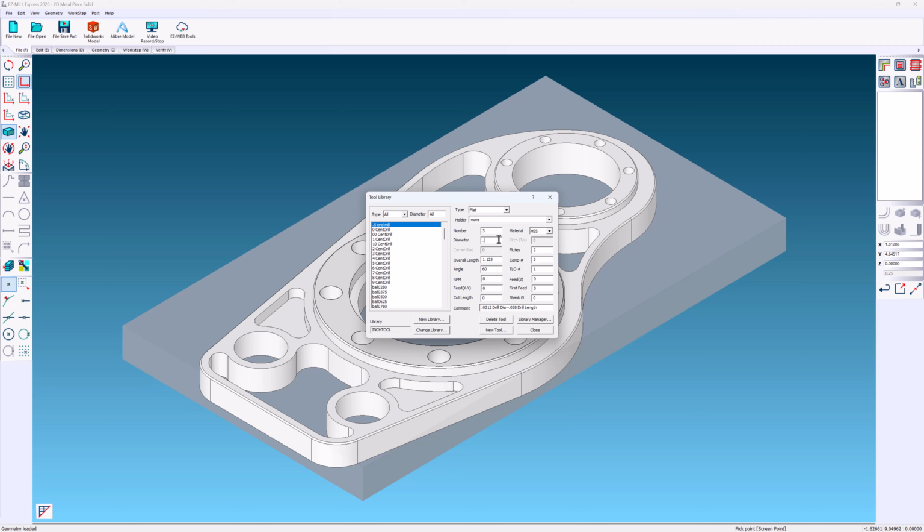Set the tool diameter, overall length that hangs out of the holder, angle if it's a tapered tool, dedicate an RPM, and feed in the X and Y, the max depth pertaining to the flute length, feed when plunging into material. If you look at the shank diameter, an excellent example would be a key cutter. And maybe add a comment. All of these settings can be changed on the fly if need be.